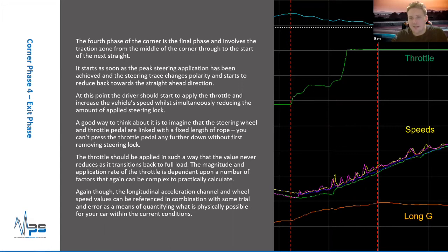All that's happened there is the car's still trying to turn, the front corners are still trying to create a slip angle and get some cornering grip, and then as soon as you pick the throttle up, the car will naturally squat and transfer the load to the rear, and now the tyres which hadn't finished cornering in the first place have got less load on them, less available grip, and the understeer just builds.